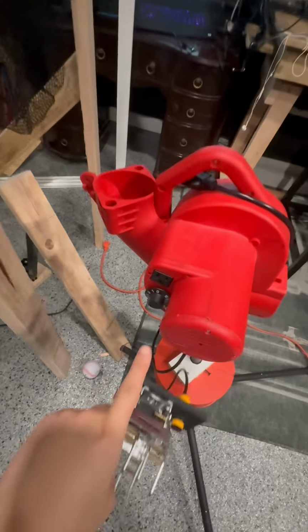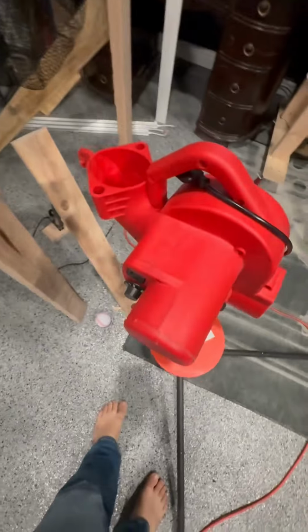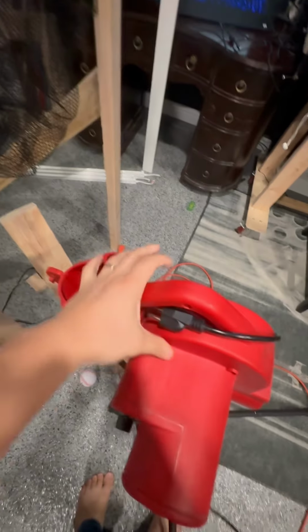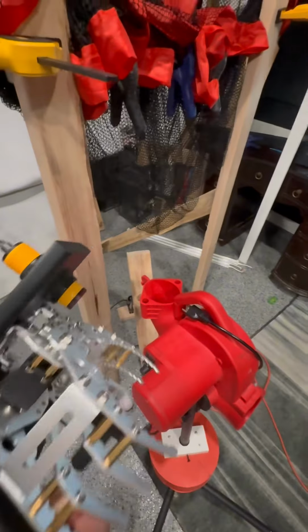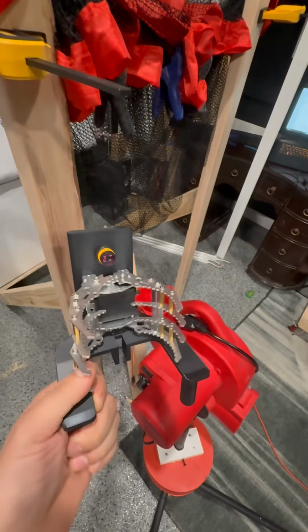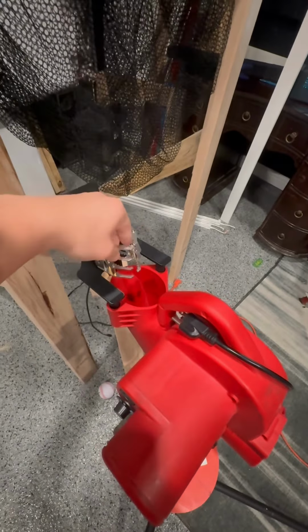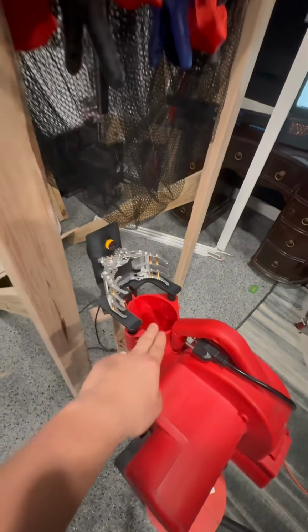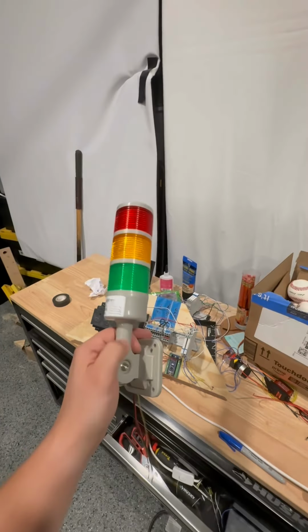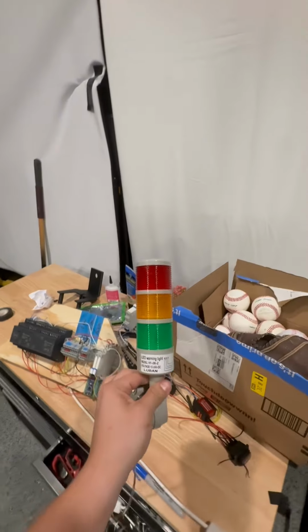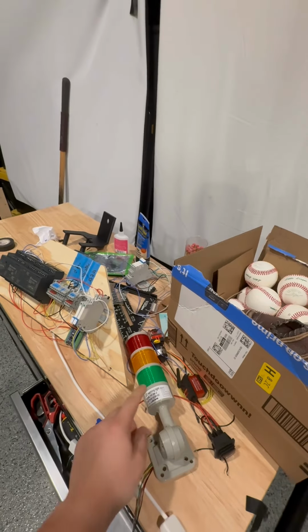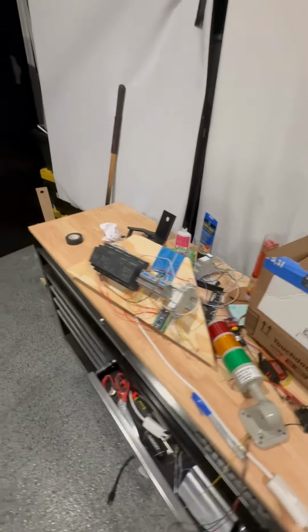Then the pitching machine itself will need 1 digital output so we can switch the actual wheel on and off. And then we're going to have a digital input tell us when there's a ball in place, and then a digital output that tells us to release 1 ball at a time to go into the pitching machine. And then so you can tell a bunch of statuses from anywhere on the baseball field, we're going to add a stack light that has a green, yellow, and red digital output.